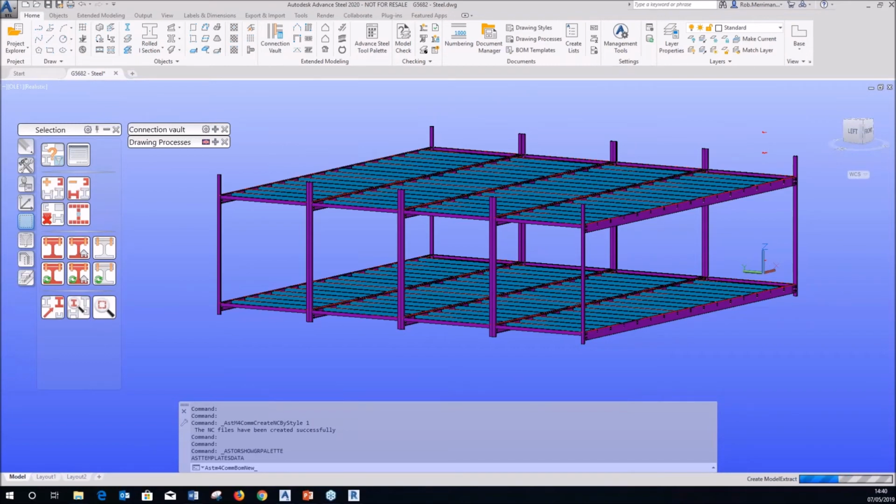I will just run you a couple of lists today. The material list is similar to the material takeoff you can do in Revit. It does give you the finished fabricated length, the length you actually need to cut to fabricate, but in terms of what's shown in that list, it's very similar to what you can do in a Revit schedule. But the assembly and delivery lists, I'll give you a quick preview of now. It's nearly finished, and I'll get the other one running while I'm showing you this assembly list.